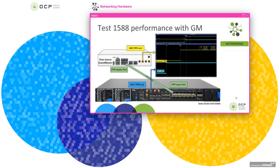time synchronization. But how do we measure it? You can see another yellow and blue line here. That is the 1 pps output. It is hard to measure the central timing of the machine from the packet, so we will use 1 pps to measure it, because 1 pps indicates the nanosecond rollover point for each system.